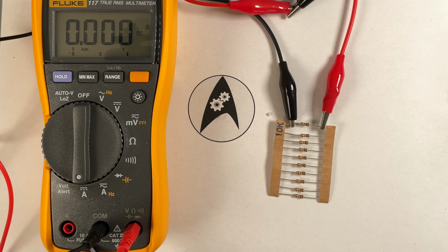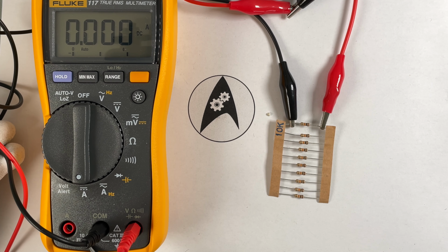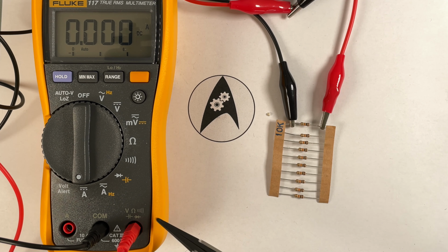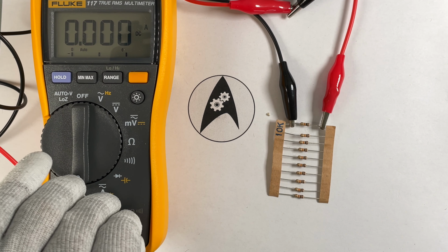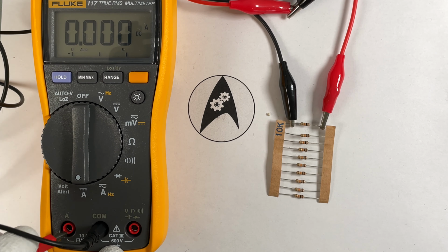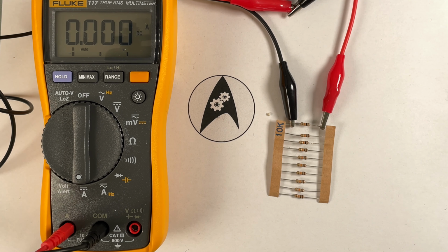So we have a maximum of 10 amps which we can safely let flow through this multimeter before the fuse blows. But in this setting here, even though we have adjusted the rotating selector wheel here, we cannot measure current flow. In order to do this, we need to plug the cable to the left side. And now we are good to go. Let's activate the power source.